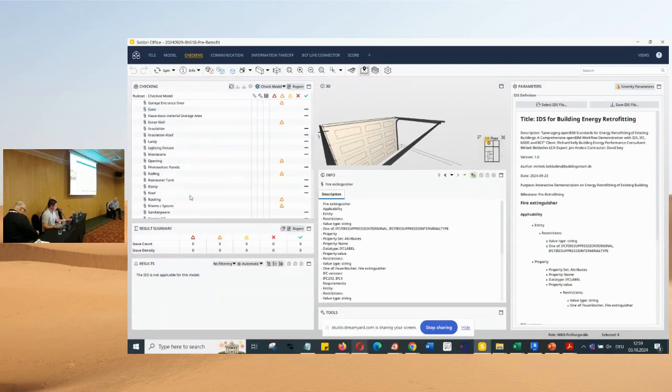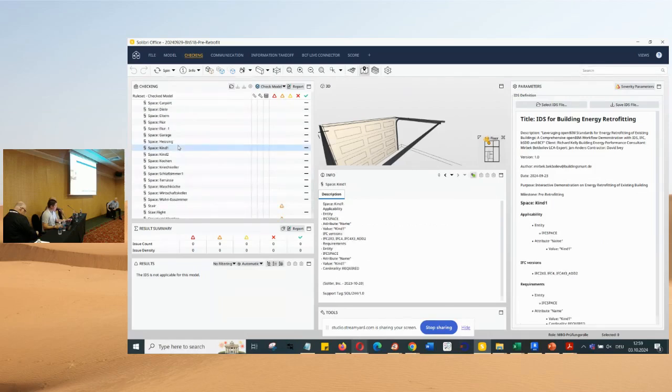And let's go to one case where we have the first important thing. We captured that there was a naming convention for all spaces. We captured that precisely, and we don't have any issues with them. We have all rooms properly named in IFC space. Why is IFC space important, by the way, for energy simulation? There is especially one case, second-level space boundaries. You will be able to know what the building materials are, what the next layers are, and what the adjacent place has, windows and other places.